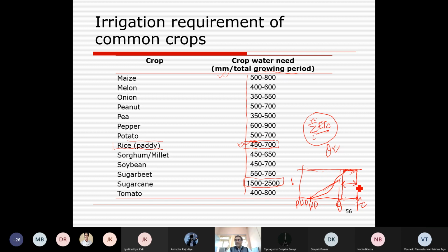or simply, if we are counting the days, we can accumulate the amount of evapotranspiration to reach that soil moisture. Like at field capacity, suppose theta field capacity is the moisture content, you can find out how much water there is per unit depth, or for a specific depth D or Z in terms of root zone.